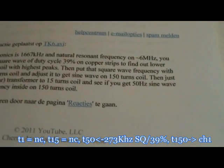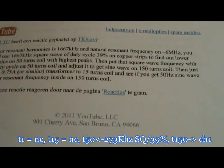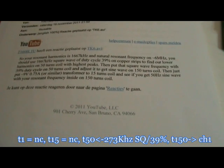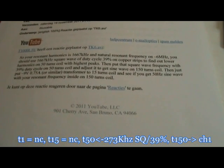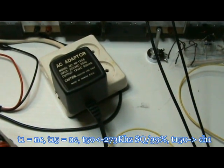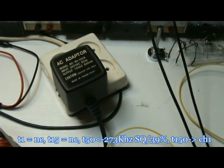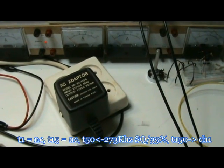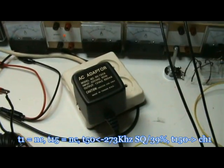The next thing he asked is to put the 50 hertz on the 15 turn coil and see what's happening then. So I have an AC adapter, 12 volt AC, because when I put in 50 volts for 50 hertz from my sine wave, nothing happens, it's too weak.